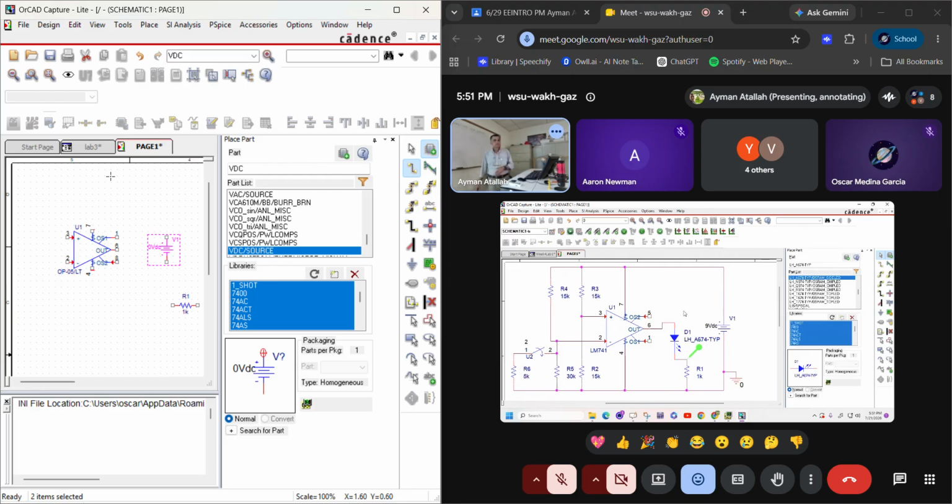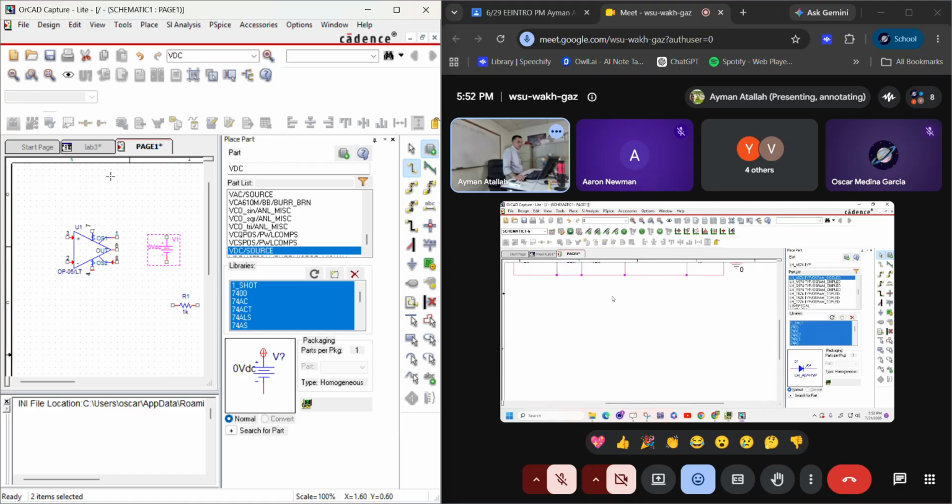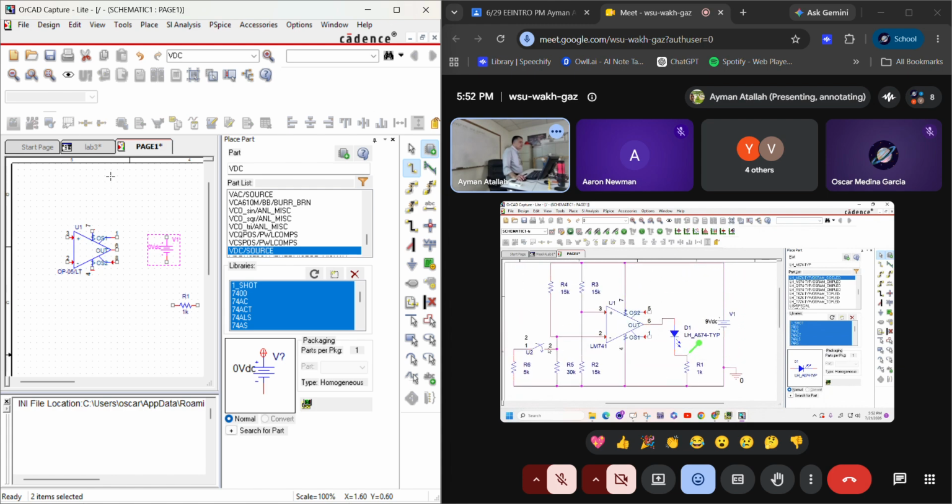So if you connect a motor here instead of this, will it run? Even if it gives 10 volt, like you can change this battery voltage to 10 volt. Will it run or not? The motor needs 1 ampere, but the maximum current we can get from the operational amplifier is like 20, 25, 30 milliampere. But we need 1,000 milliampere, which equals 1 ampere. So we cannot use the operational amplifier to run a motor. If we put a motor here, the motor will run on and off.